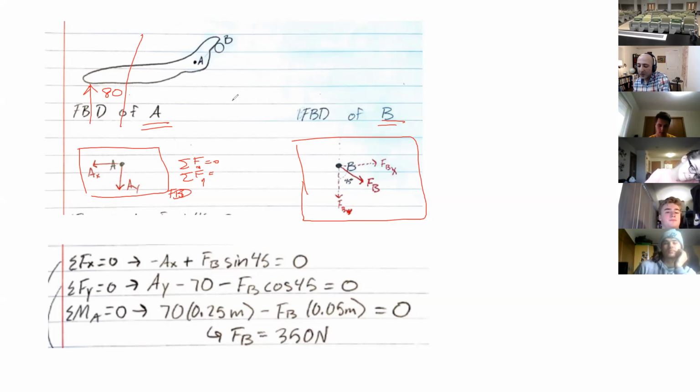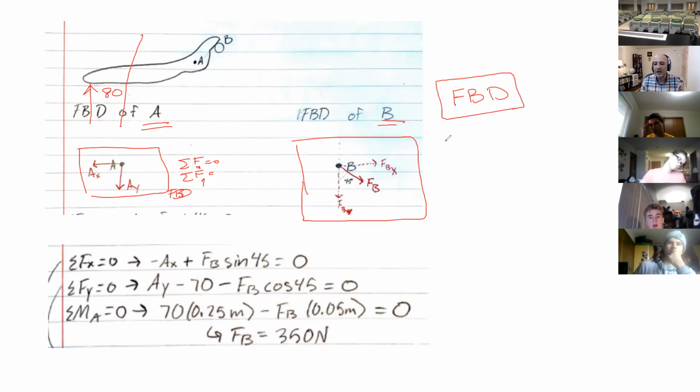The important message is, again, this is not to embarrass you guys or make fun of the solutions. You're trying to learn from it, okay? The important thing to learn is you have to follow the 3 steps of a free body diagram. Absolutely. Step 1 is to isolate and draw an outline of whatever you're working on.